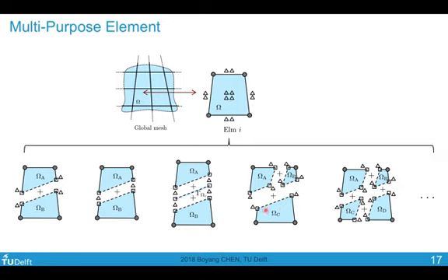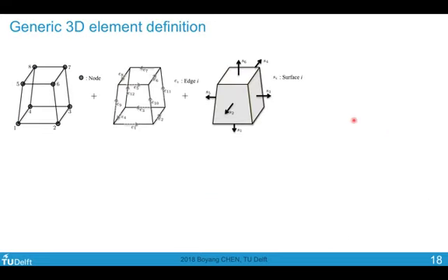So here you would have 3 integration domains, and here you would have 4, and it's your choice to subdivide your original domain into different sub-elements. And as far as the solver is concerned, the solver is only seeing this big element. So this is a flexible way, and we can further extend it to the 3-dimensional case.